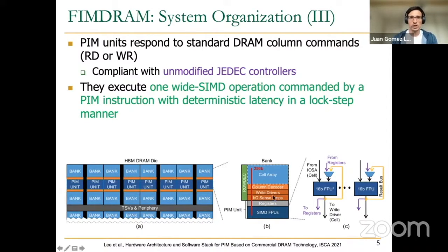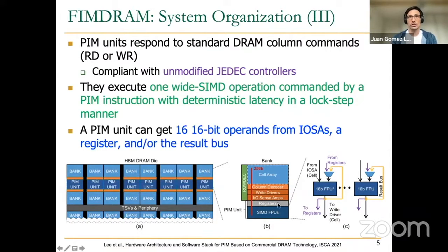And here on the slide, you can see a representation of the DRAM bank composed of the cell array, and here we see the column decoder, write drivers, and also input-output sense amplifiers, from where the SIMD FPUs of the PIM unit are going to read operands, same as from these registers that you can see here.